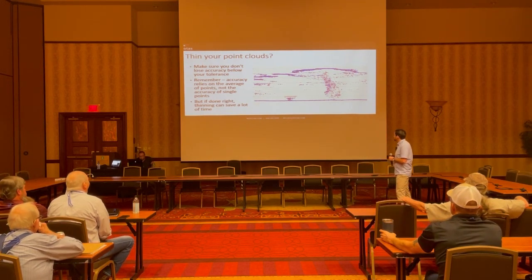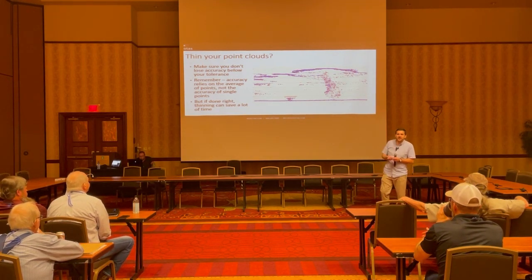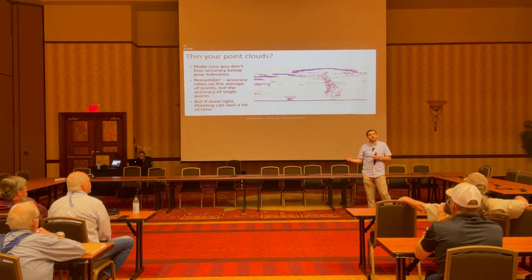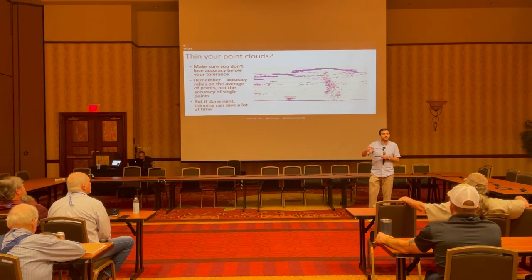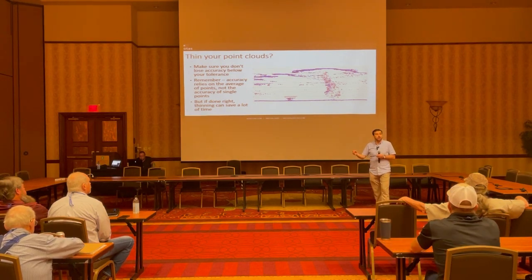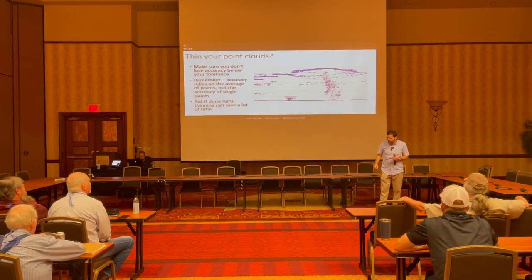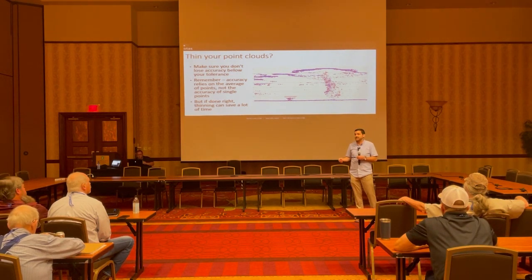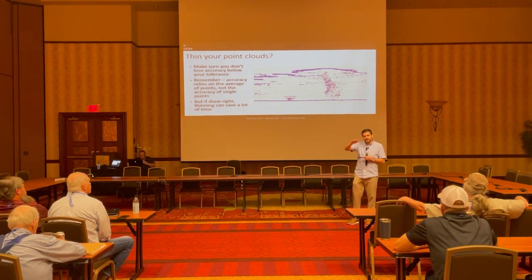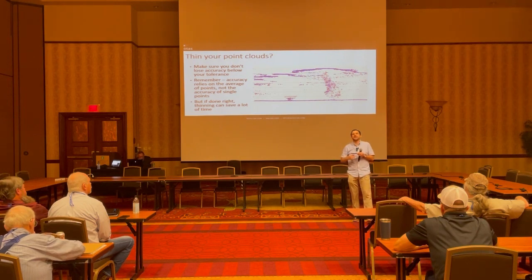There are also more advanced methodologies that take denser areas like trees and thin those more aggressively, but in areas where it's sparse, they don't thin as aggressively. Those are really cool and sound smart until you look into the data and see that they can introduce biases, where it takes a nice surface and can actually split it into high and low points and create a kind of dual terrain.